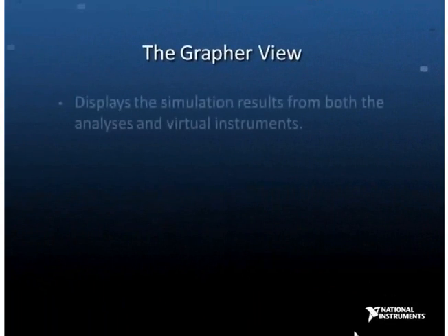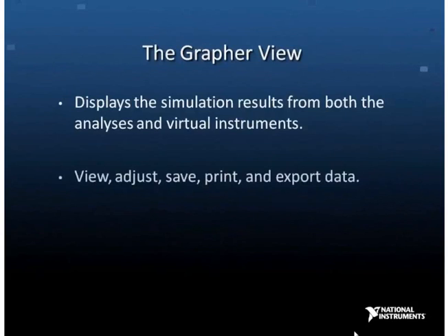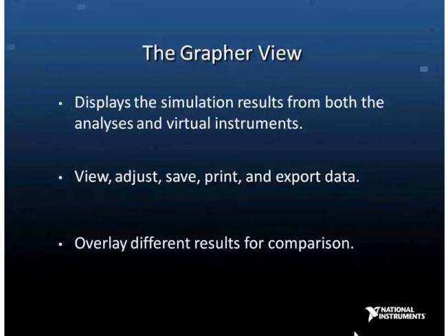The graph review is not only for the visual display of the results from analysis, but every time a simulation is run, it saves the data gathered and displayed from the various instruments, such as the Bode plotter or the oscilloscope data. It can be used for precise cursor measurements as well as the management of the data through saving, printing, and exporting to programs like Excel. You can compare more than one result with overlay functionality and create annotations and even place data labels.